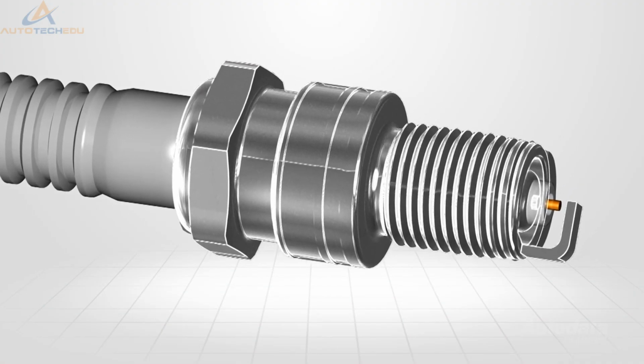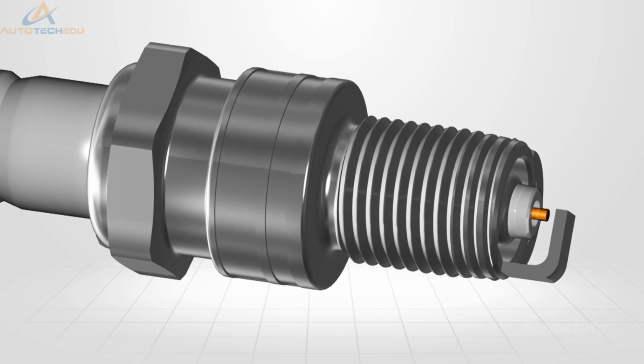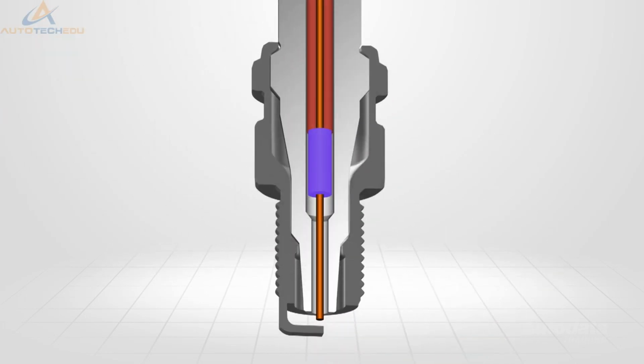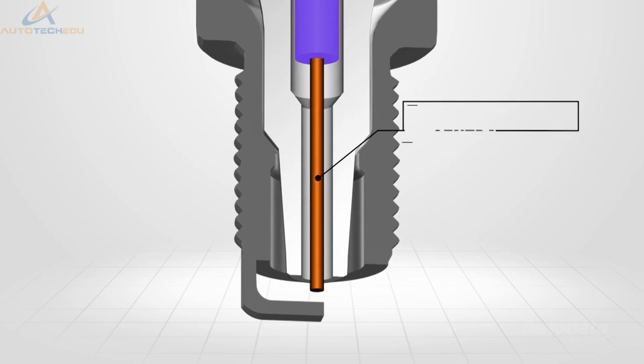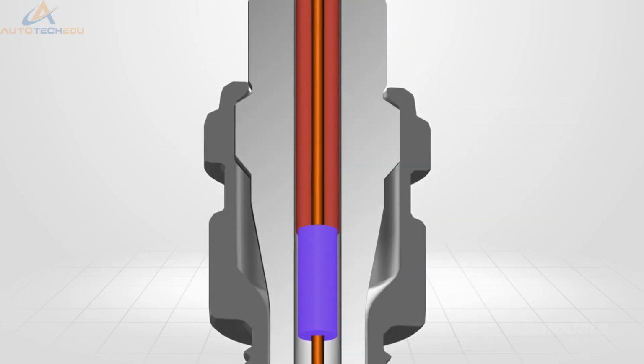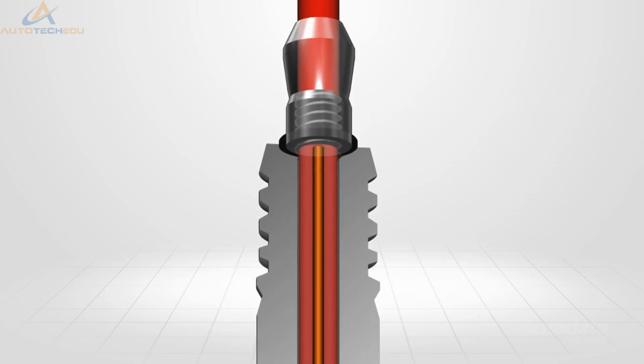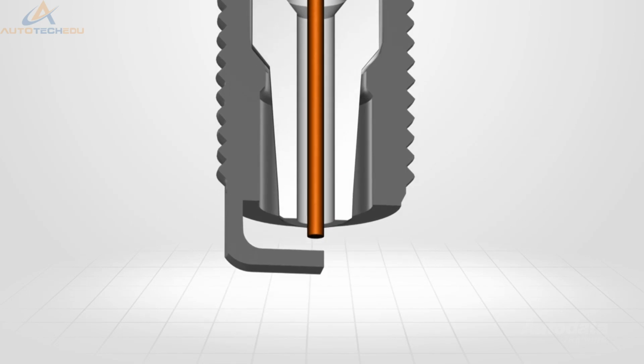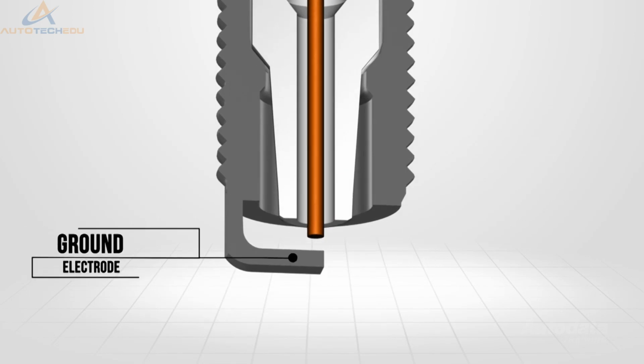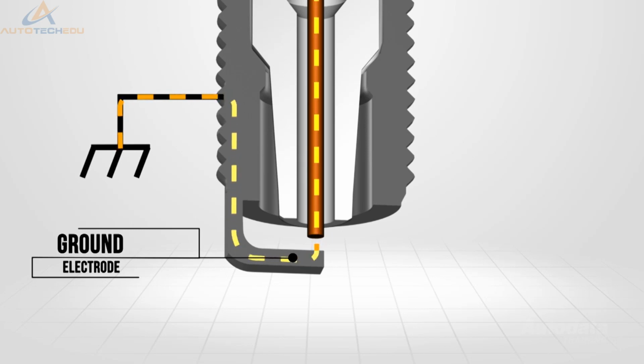The metal shell is designed with the thread that screws into and seals the combustion chamber. The seal may take the form of a compressible washer or a tapered seat. The shell holds all the spark plug internal components in a neat package and acts as the earth point to the engine. Within this shell is the insulated central electrode, which protrudes through the insulator into the combustion chamber. The electrode is connected to the terminal at the top of the plug. The shell may have one or more ground electrodes built into the side. These allow the current to travel to earth and complete the ignition secondary circuit.